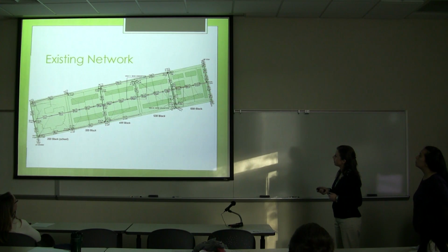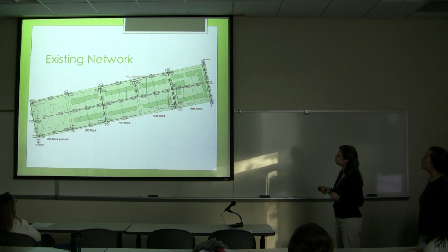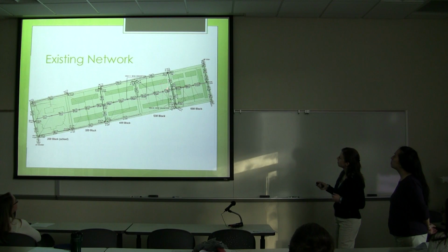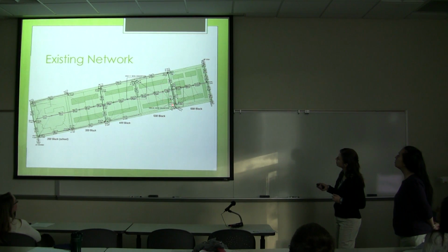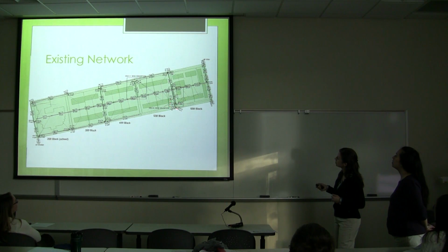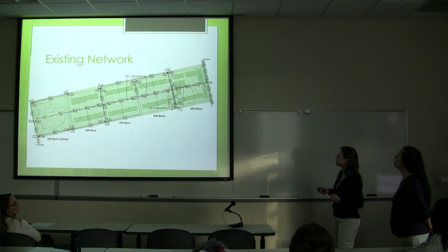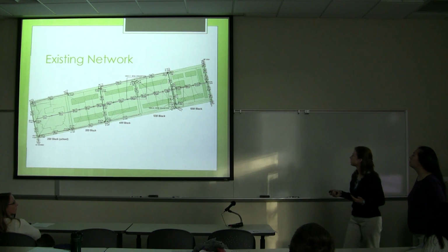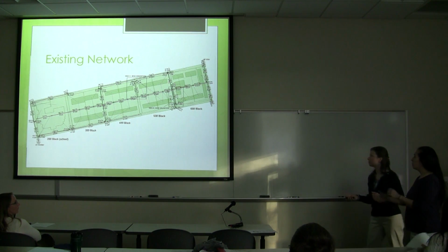And you can see how we have grouped our houses into groups, usually 5 or 6 houses per block, except in the area right here. It's hard to see in this graphic, but right there we did take a little closer look since we were concerned about surface runoff into these catch basins. So we did separate this house, and we're a little bit careful about the way we directed our overland storm runoff flows. And I think Lee is going to talk about what we found.